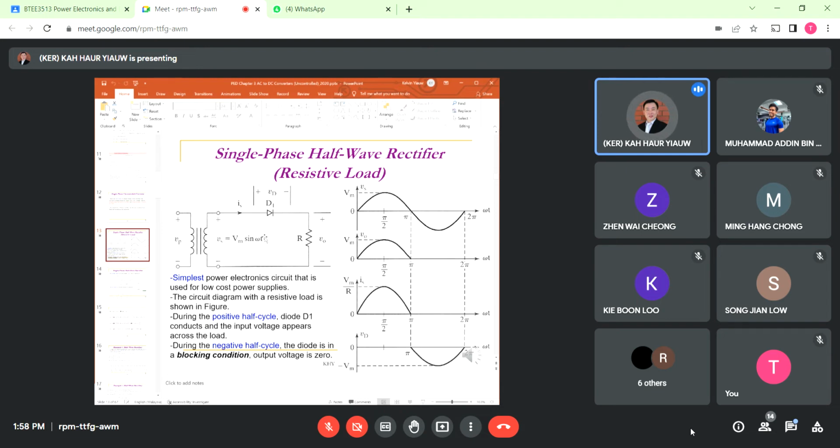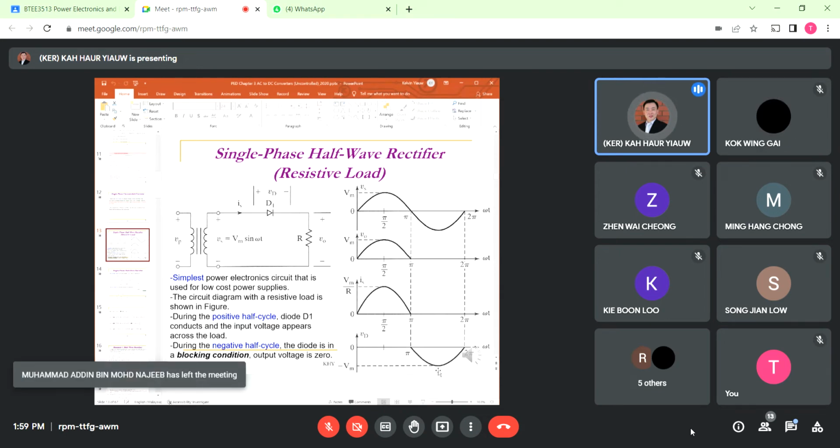However, this time when you are measuring the voltage across the diode, with the positive probe here and your negative probe here, you should measure that there is a negative value of the ripple appearing across this VD. So the maximum value is also equal to the VM. Okay, so does everything make sense? No problem?